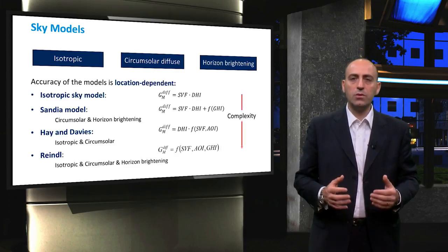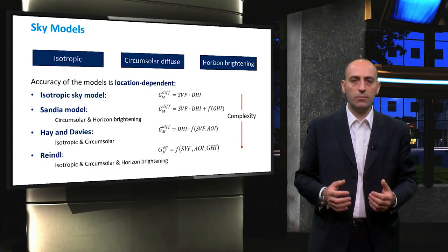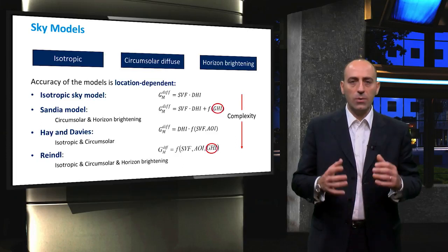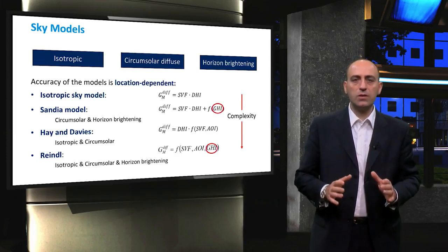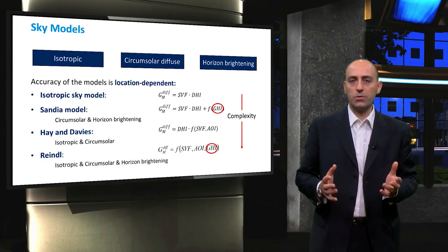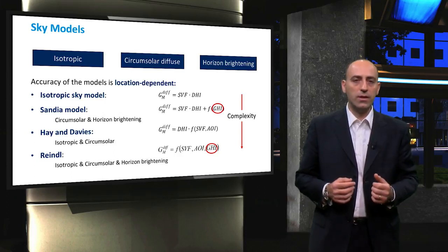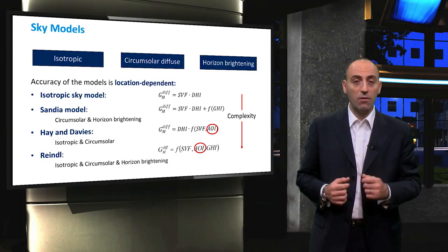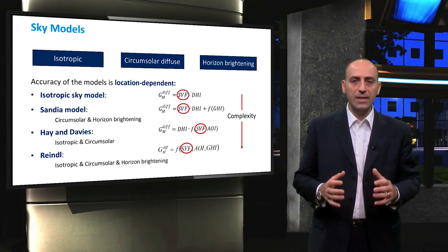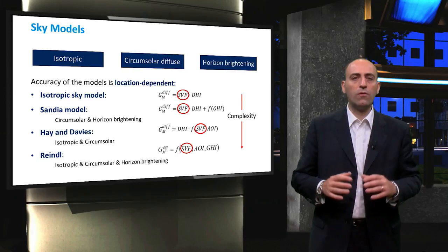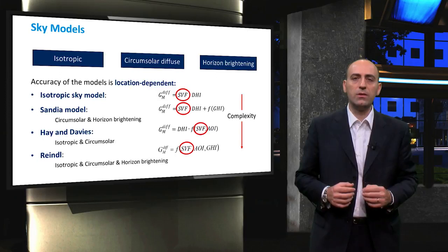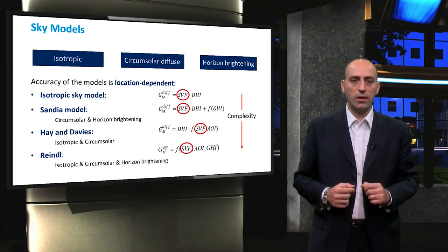To calculate the diffuse irradiance, several models have been developed, each based on different principles and varying in complexity. As we have seen in the previous videos, for each of these models, one or more input parameters are used. These are global horizontal irradiance, or GHI, diffuse horizontal irradiance, or DHI, angle of incidence, AOI, and the Skyview factor, SVF. Among these, the only input parameter common for all the models is the Skyview factor. Hence, it is a very important parameter that has to be calculated in irradiance modeling.